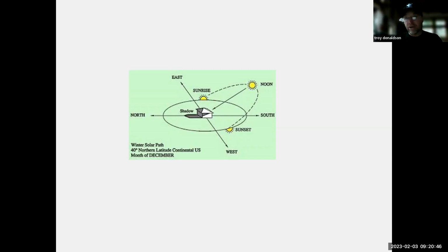And what I'm going to have you do is calculate it. You're going to go outside with a stick. You're going to put the stick vertically straight up and down, and you're going to measure the shadow. So you know the length of the stick, you'll measure the shadow, and you'll do some basic trigonometry to come up with the solar angle. Note the time and the day that you do it. Even on a cloudy day, today's cloudy, this can be done. You'll get a shadow, but you need a good flat surface. So try to find a flat horizontal surface. Try to do it at a time where the sun is nice and high, and stick your stick up. It'll make a shadow. Measure the shadow, know the length of your stick, and you can calculate this solar angle that we're looking for.